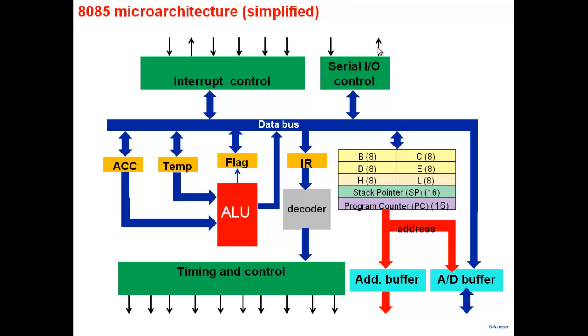All right, so if there is an LED and, for whatever reason, you want to make the LED blink, LED blink means you give 1, 0, 1, 0 in a particular order, right? So the microprocessor can send data here at this particular point. This can go to the LED circuit and make the LED blink on for a certain time, just as an example that it can communicate with the external world through the serial input output. It can communicate with the external world through these 8-bit lines also. These 8-bit address and data buses can also go to the external world besides the memory, and you can communicate through that as well.